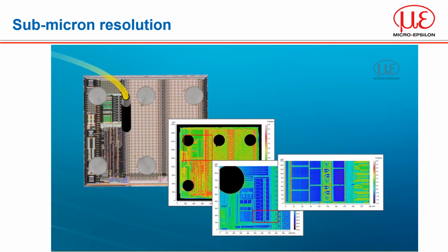Linearity of confocal and laser sensors is very similar for a given range, but the sharper, more consistent spot provides a greater stability, which is why the resolutions are so much better compared with laser triangulation sensors. In addition, a laser sensor might have a smallest range of 2 mm, whereas a confocal sensor can be as small as 100 micron. So even linearity can be improved against laser sensors when using the shorter measuring ranges.